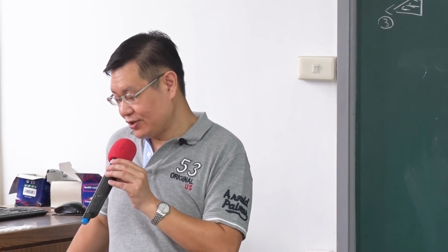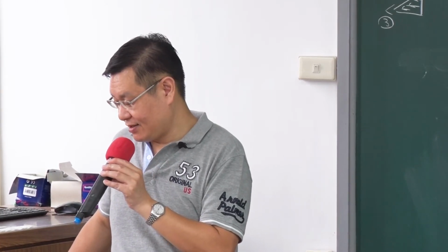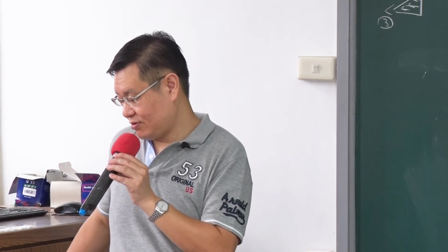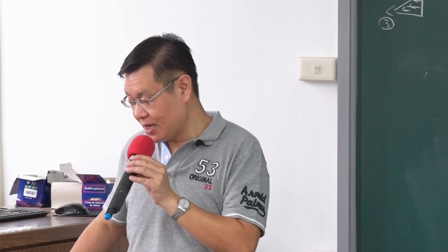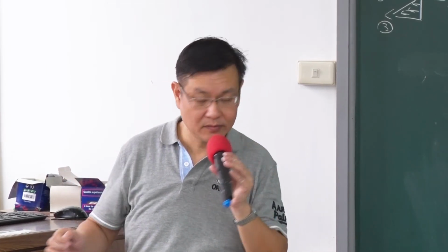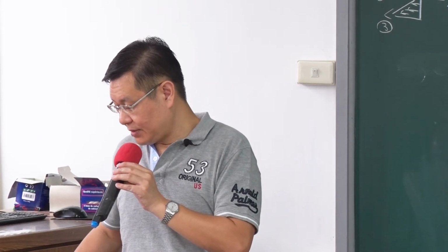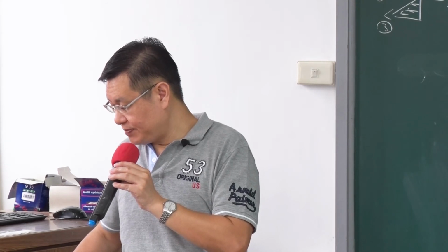But in our case, we are not using single crystalline silicon. Actually, we are using polycrystalline. For polycrystalline silicon, it's not that high. It's ranging from 15 to 25. It's one order of magnitude lower than single crystalline silicon. However, it's still one order of magnitude higher than only using the structure change. Remember, structure change gives you only a 1.6 gauge factor. But by using polysilicon, you can have 15, even 25. Much larger. Okay? And another thing about the sign is that n-type and p-type silicon have opposite signs, n-type being negative.